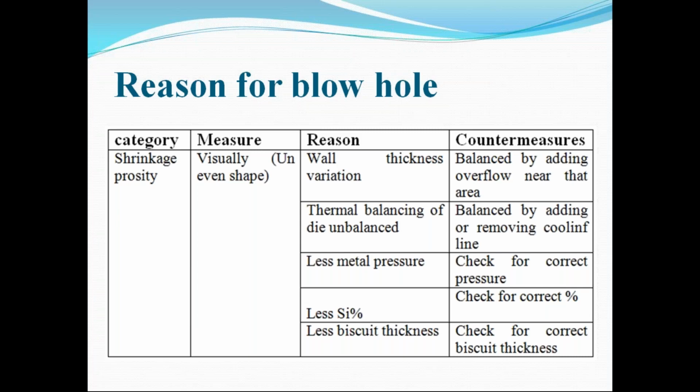Okay, so then heat, that means heat transfer happens. The third one is the duration of cooling and lubrication spray on the die, and the fourth one is die exposure again to the ambient environment before the next cycle begins. Okay, so this process of heat addition and removal keeps continuing in equilibrium for the sake of good quality of casting, to increase die life and to increase casting strength.